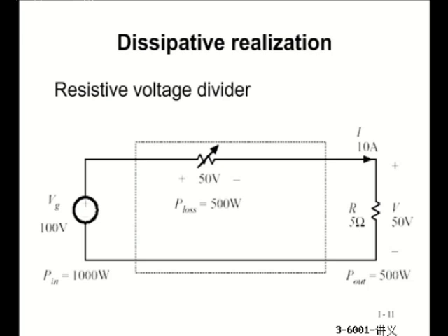Okay, so now, this solution, in order to handle the disturbance, as I said, one type of disturbance could be coming from the changing of load resistor. Another type of disturbance may be coming from input voltage. So when they are changing, how can we be sure the output voltage, load voltage, is still exactly 50 volts? This is hard. This solution is quite hard to realize automatic control.